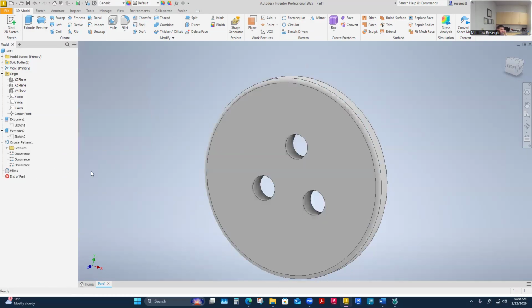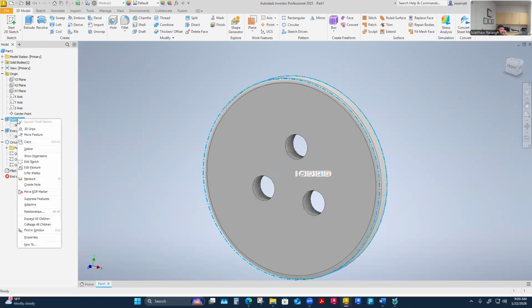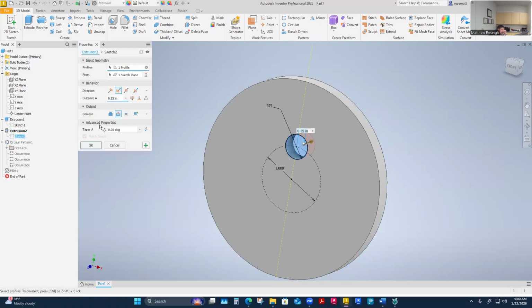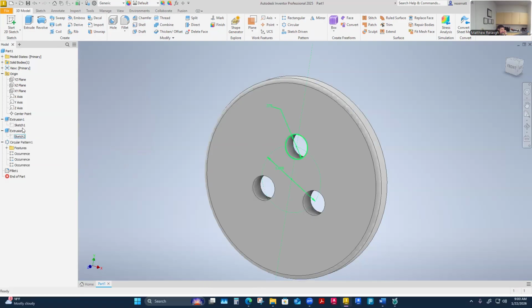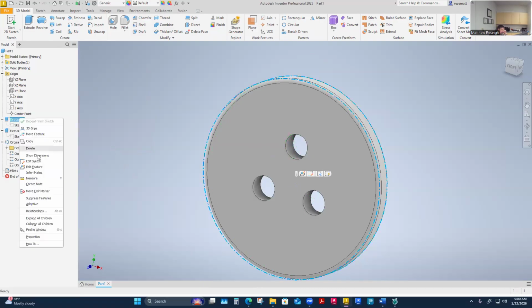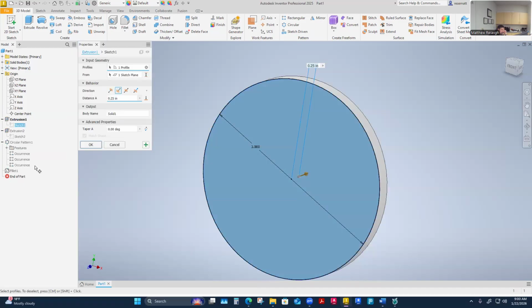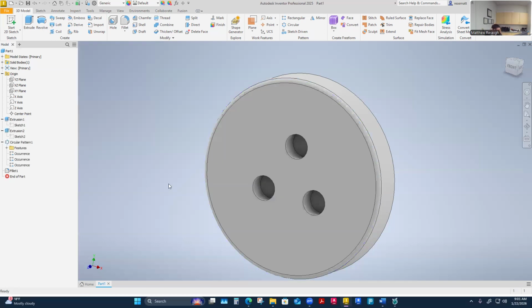No, it doesn't. I didn't do a through hole. I did a 1/4 inch. I did it kind of like the book did. This extrusion's actually at an actual 1/4 inch dimension. Then if I do what they're having me do, which is edit this feature, we want it to be a half inch thick. So I'm going to change the 1/4 inch first extrusion to a half inch, which is just a matter of right clicking, entering. The profile I don't have to change or anything. Just say okay. Now I've got a half inch, but then I have no through holes.